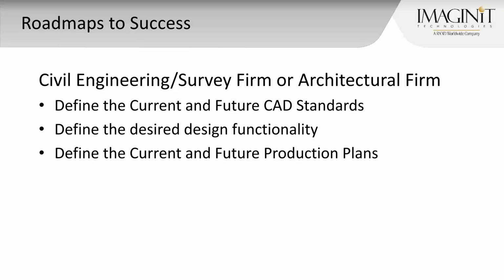We want to make sure that there's a seed file that contains the CAD standards, or most of the CAD standards that we have, and we will create a DWT file that has the CAD standards for AutoCAD. And so again, making sure that we cover everything that's going to be translated through there. Now once we build these translation tables, the way we do it is we'll have a folder structure, and we will run the translator through that. And so we want to make sure that we're getting the clean translation.